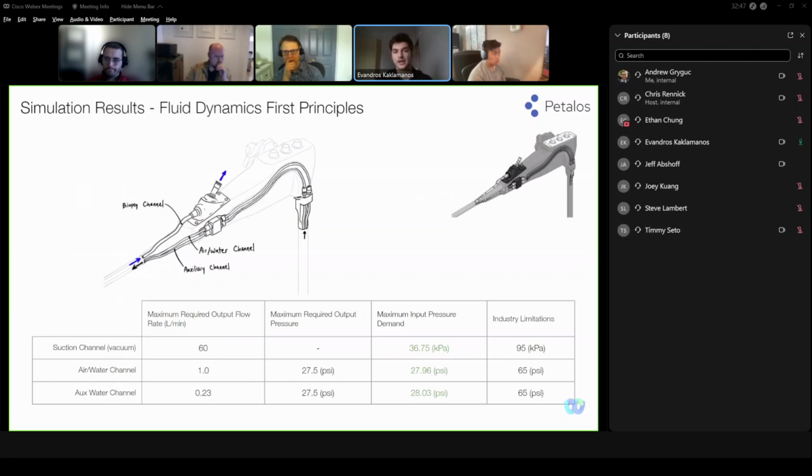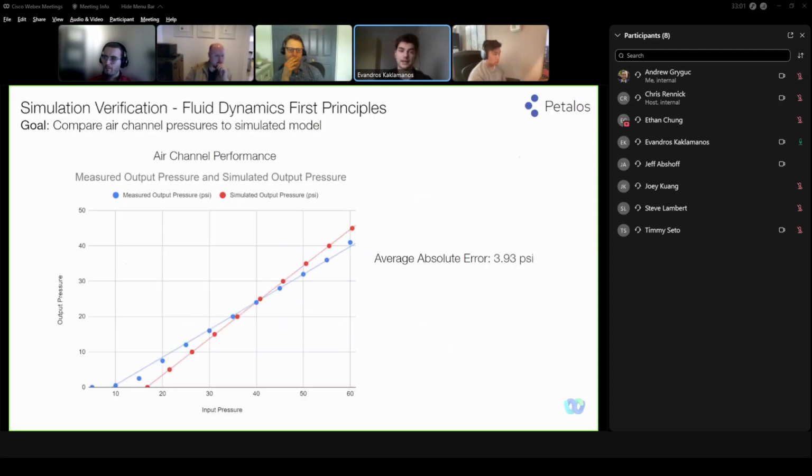Flow through channels demonstrated that our design is viable and allows for the normal function of flow through the channels based on current industry standards. Our model validates that even with our changed channel design, we did not impose issues regarding channel functionality. Again, we were able to validate our model during the prototype assembly phase. We tested channel pressures with pressure gauges and recorded precise and accurate specifications, indicating the validity of our model.